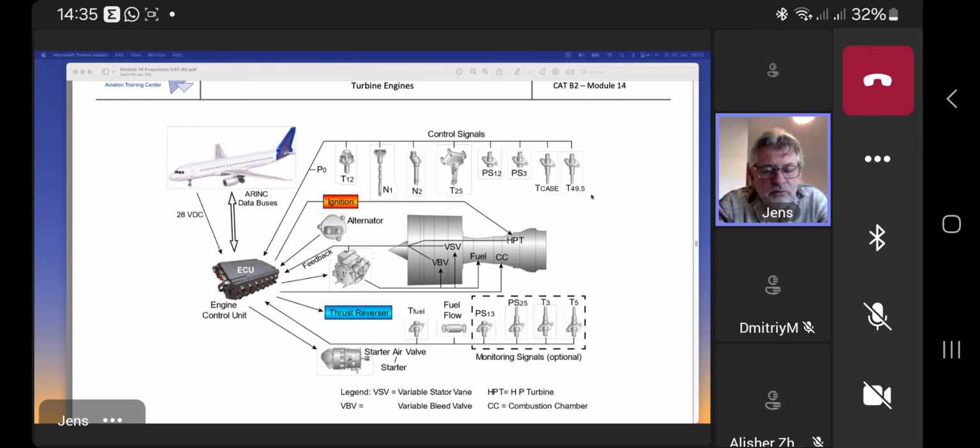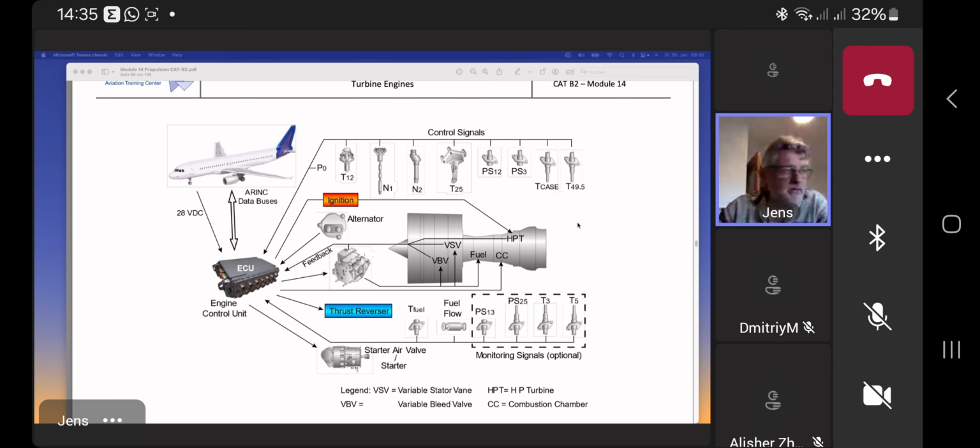For example, we have a new engine coming from the shop, maybe maximum EGT is 900 degrees, and the engine itself at takeoff has an EGT of maybe 820 degrees. So the margin is 80 degrees. The engine can deteriorate by 80 degrees until it reaches its maximum EGT. Yeah, indication for performance, and also we do not destroy our turbine.